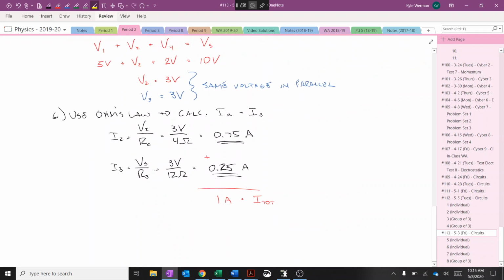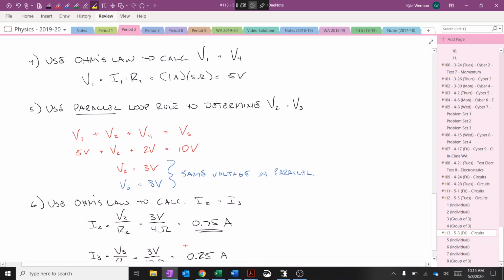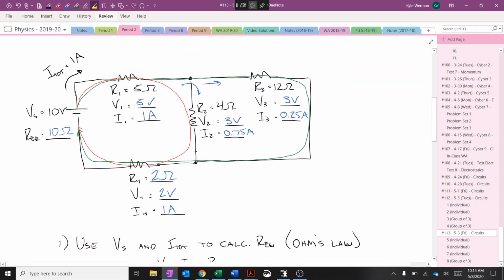So now we've gone through this circuit. We've used a combination of our series and parallel rules. Every loop drops all the supply voltage, all 10 volts. And all that current, the total current when it splits proportionally between those resistances along those pathways, but then always merges back together to get to the battery. And so now we've effectively broken down this circuit, and everything checks out and matches up using those rules.